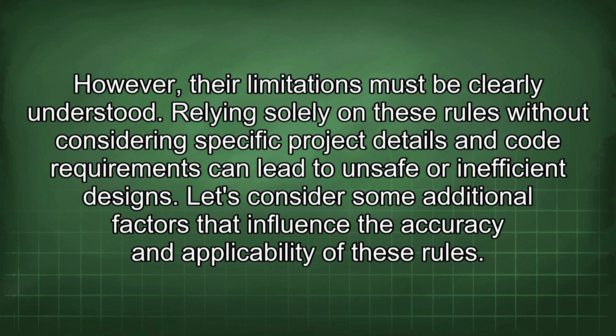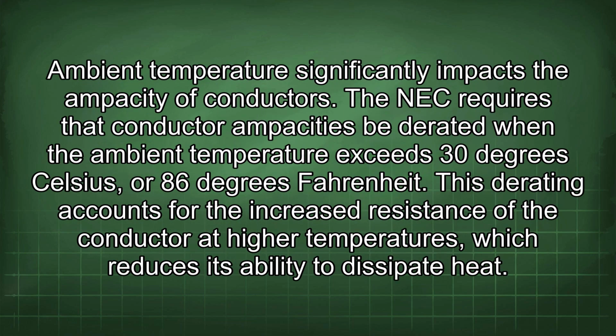Let's consider some additional factors that influence the accuracy and applicability of these rules. Ambient temperature significantly impacts the ampacity of conductors. The NEC requires that conductor ampacities be derated when the ambient temperature exceeds 30 degrees Celsius or 86 degrees Fahrenheit. This derating accounts for the increased resistance of the conductor at high temperatures, which reduces its ability to dissipate heat.